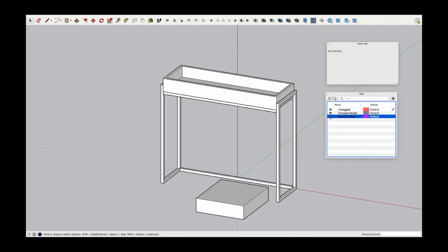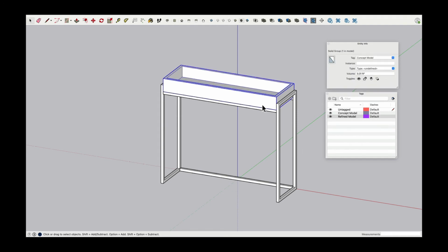Now I can show and hide the object as they should be. Okay. This is a little bit confusing, particularly for beginners. It's just the way SketchUp actually works. So again, rule of thumb, we only move objects or components to tags, and the edit pen is only on the first tag, never anywhere else. Then basically you run a safe way and you will never have any issues.